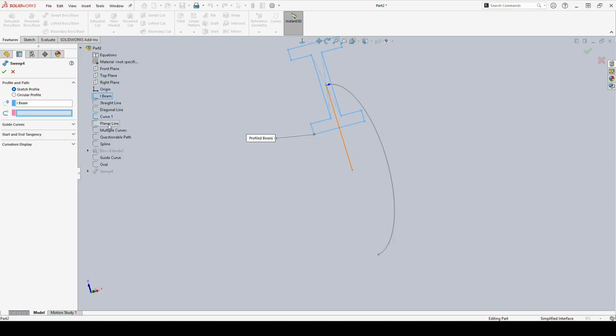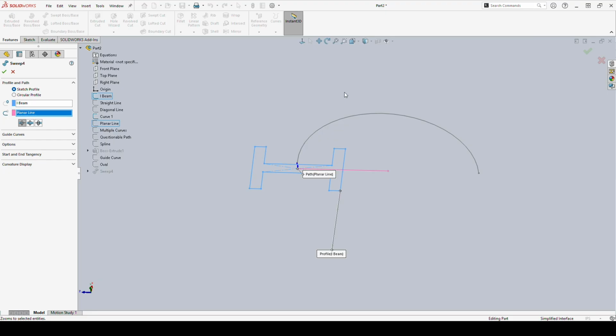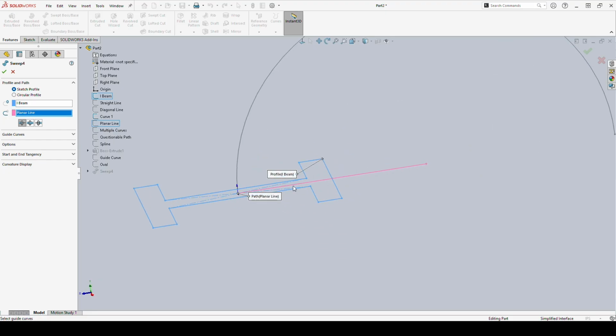Now with this, the one thing we can't do is we cannot pull it along a line on the same plane, because at this point, what we're seeing here is we're more or less not creating a volume. We're just sliding the face, and all you would end up with would be a surface, not an overall volume. So it cannot actually construct this.